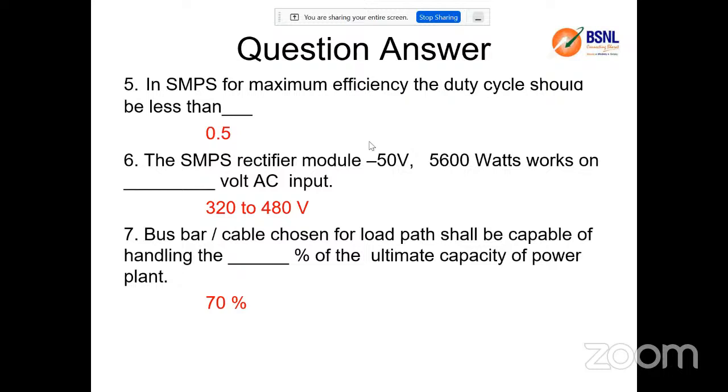I would like to say that now, in my exchange, I am buying a power plant module, whose ultimate capacity is that it is able to have 6 numbers of 100 ampere capacity. So that is the ultimate capacity. But I may not have all the 6 modules activated. I may have only 4 numbers, so that the maximum load current can be 400 amperes. So that is the difference.